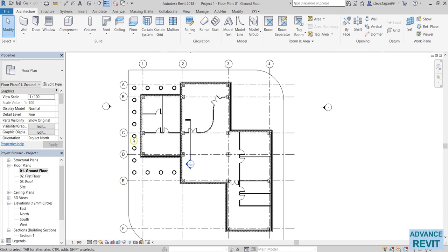So to view all of the different window tiles, if we come again back up to the quick access, there's our switch windows. So if we click on that, it will just display what current window tiles are open. If there's too many open, you can select close all window tiles or close hidden windows. You could have 10, 15, 20 open at once. What you can do is click on the close hidden windows, and that will close all of the other windows apart from the one that's currently open.